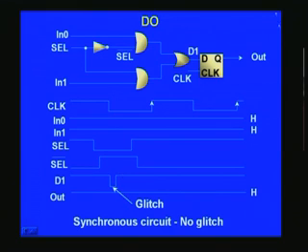and the way to do it is to put the flip flop here. What happens if there is a flip flop here? Naturally you can rest assured that there are other flip flops from which other signals are coming, or it may even be asynchronous, in which case you cannot directly put it here, you need another flip flop and then only process other asynchronous inputs, which we will see in the later slides. And here, all this glitch will happen before the rising edge of the pulse. You should keep the total delay of this in mind, and then only select your frequency.